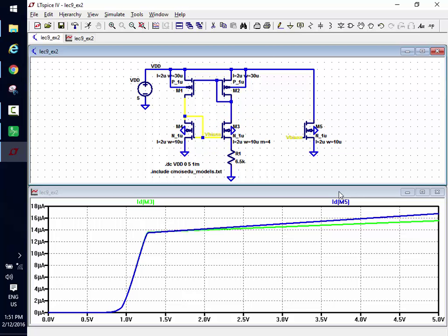You can go crazy in simulations if you have things labeled with some common name like N1 for node 1, and you're using it in several places. It means they're shorted together and you just can't tell. Does everybody follow this? Does everybody see how I would use this to generate a current? I would think of this point as a current source, and then I would ask, VGS is 1.05. What's the minimum voltage I can have right here in order for this to behave like a current source?